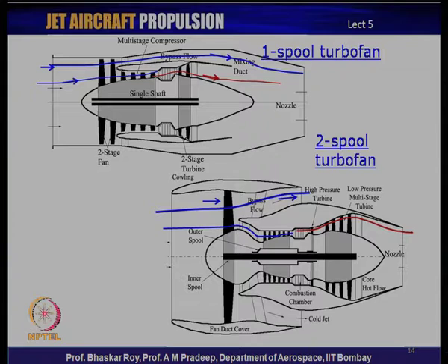So, the thrust production is of a slightly higher order, and as we have seen before, this simple method of bypassing a certain amount of flow and later on maybe mixing them produces a certain amount of SFC benefit, a specific fuel consumption benefit, and that benefit people have been trying to harness for a long time by various versions of turbofan engine. So, various versions of turbofan engines are typically bypass engines. So, that is another way of looking at turbofan engines. We can look at them in terms of spools, or we can look at them in terms of bypass, the amount of bypass they produce.